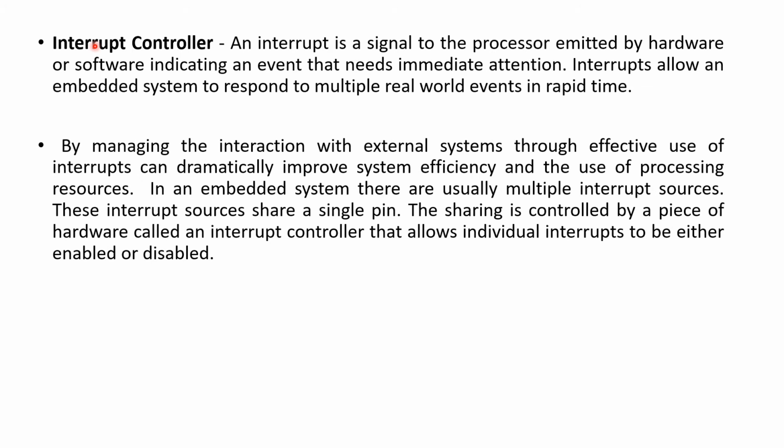So we have seen the clock oscillators and the timer circuits, and another component is the interrupt controller. Although we are saying it separately, the interrupt handler is also basically a timing device. The interrupt handler has to handle the interrupts. Simultaneously the system is performing many tasks, but in between something goes wrong or something needs immediate attention. That is what we mean by an interrupt. It can be emitted by hardware or software. Usually when we talk about interrupts, we commonly refer to hardware interrupts. Software interrupts are also called exceptions.